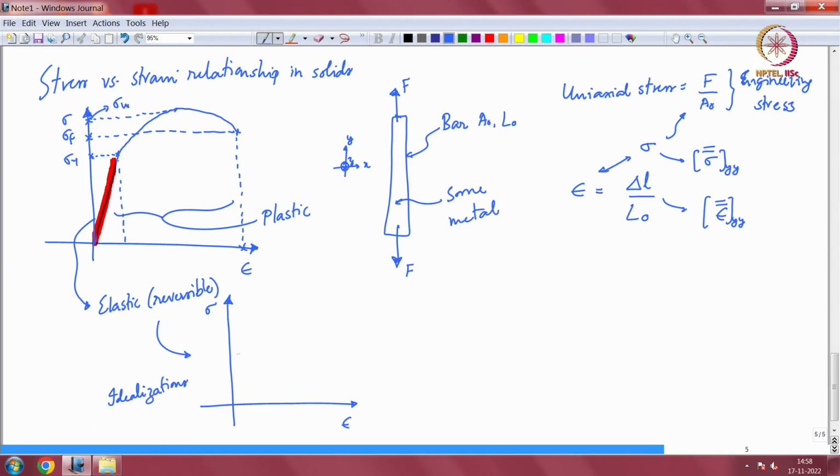The first one is what we will call this. So, this is what is called a rigid perfectly plastic material. Basically, what this says is that the elastic strain is almost 0. So, if the elastic region for your particular material is small, you can approximate it like this, and the material does not have strain hardening. So, this curve is sort of flat. If it is reasonably flat, you can make it look like a step function like it is here, and this idealized model is called the rigid perfectly plastic model, okay.